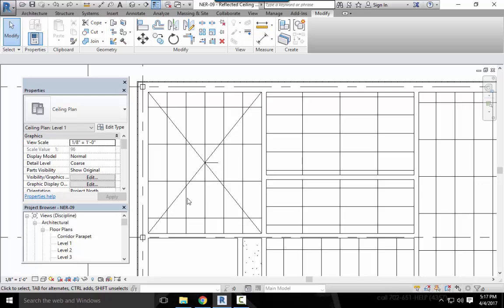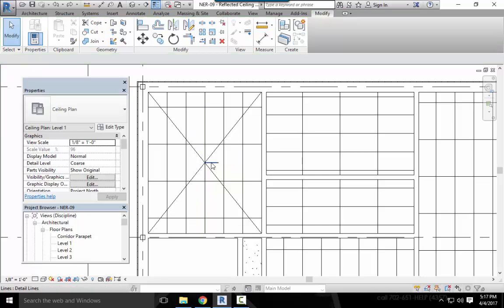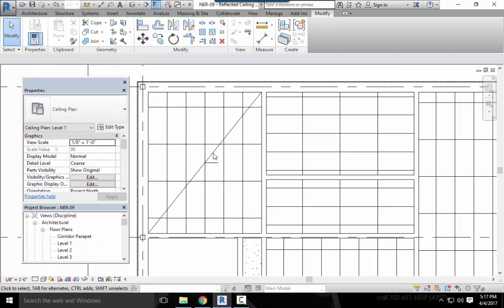So everybody understand how to adjust this grid? Okay. You offset 24 inches. Is that where you went? I offset this detail line 24 inches. Okay. And what you're going to want to make sure is when you're done with these detail lines, delete them because they will show up. Get rid of them. They were really just there as a drawing tool for you.